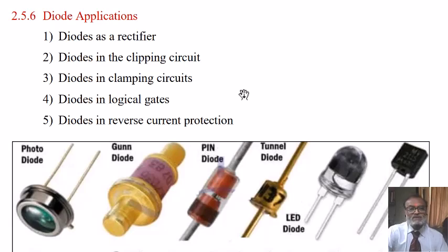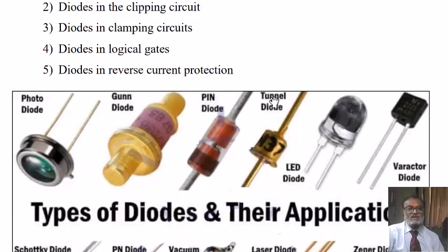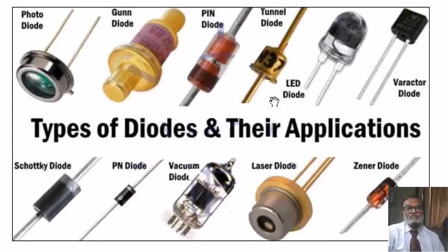Since a diode conducts in the forward direction only, if we insert a diode in series with any current path, it will not allow the reverse voltage to be applied to the circuit because it automatically goes into the open circuit state, thus protecting the circuitry from reverse voltage or reverse current. Typical practical diodes look as shown in the figure.